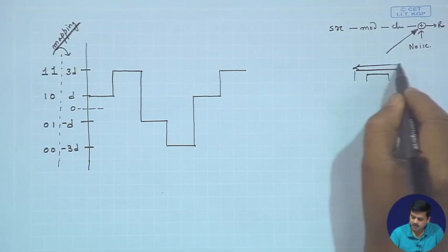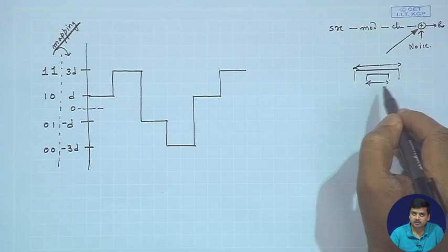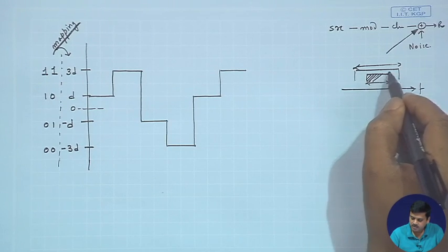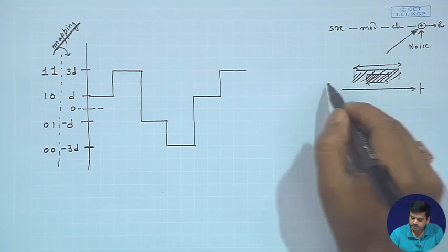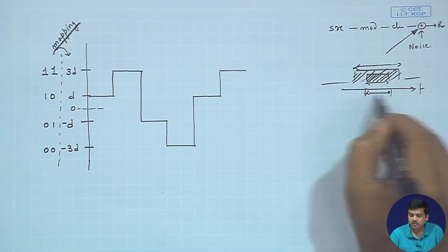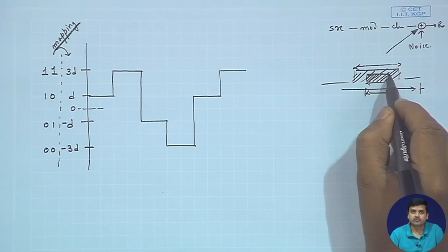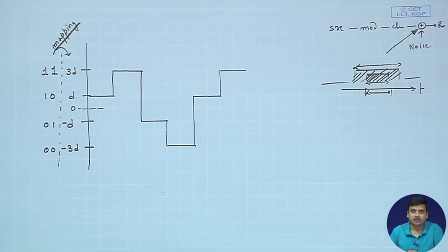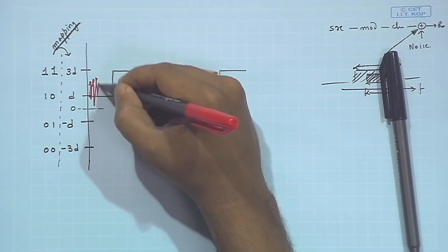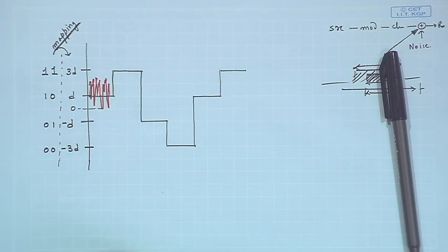This is the filter width, this is the signal bandwidth, if this is f, and this noise also passes through this portion and noise is not passed through this portion. So, in the portion of the signal, whatever noise is present is white, we could say that. So, that is a narrowband and white noise which has Gaussian PDF, and it is white within the band of our concern. Okay. So, getting back, additive white Gaussian noise could produce a time domain waveform which is like this,